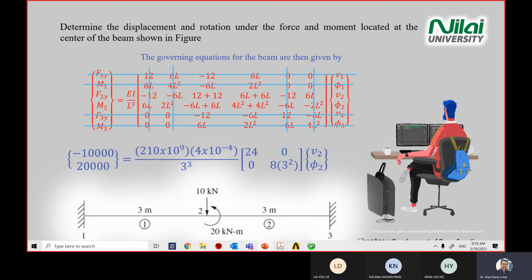Yeah, so this positive negative notation is the most common area that students make mistakes when it comes to tests. So be careful on the notation. Don't just copy the magnitude and then forget about the direction. Negative in this case going down. M2 in this case is anti-clockwise. So anti-clockwise is positive in this chapter for moment. So you carry the positive, and then the rest is just substitution of the numbers.